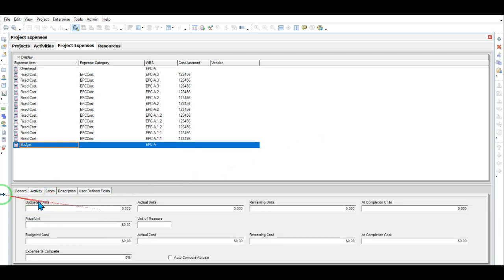Keep in mind, since the type of this budget is revenue, you should enter this value in negative format. However, for the overhead, because it was a cost value, we entered it in positive format, because by default the cost is considered in this view. But for the budget, it's enough that you enter the calculated value, considering the 20% profit, and then enter it in negative format.